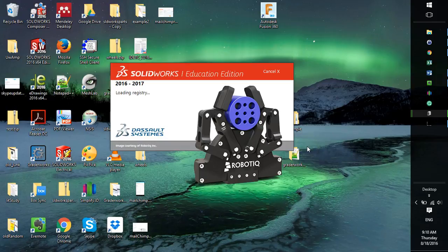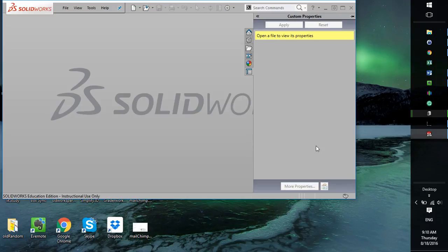Once you start SolidWorks, if it's your very first time, it might ask you about a license agreement, and if that's the case, just click accept. It might also ask you if you want to have the quick tips turned on, and the answer is no. It also might ask what units you would like to use, and for this class you can select IPS. So that'll be the inches or the English unit system. So when SolidWorks starts, it should look something like this.